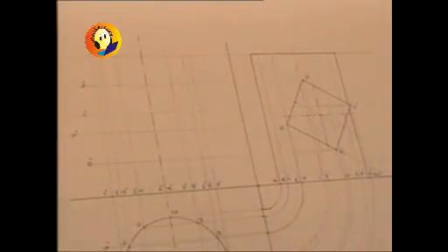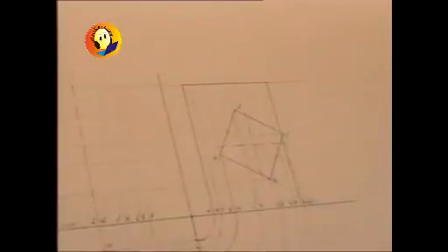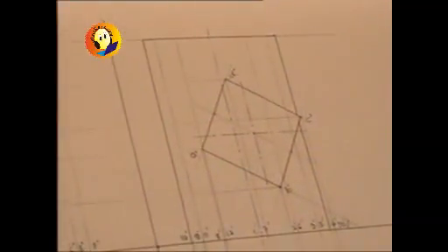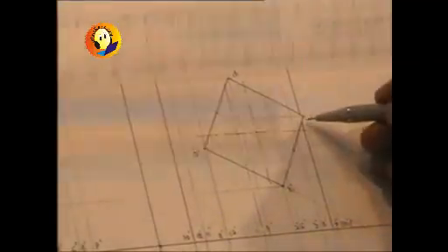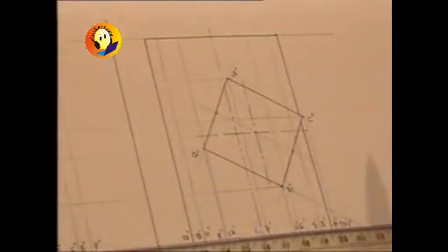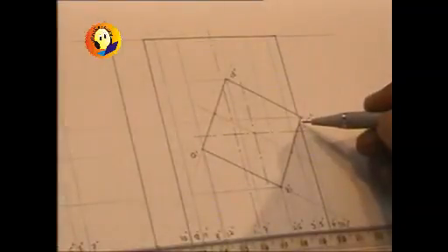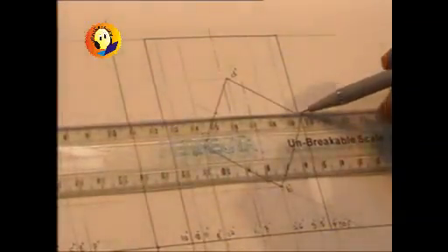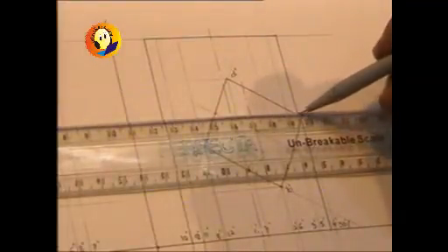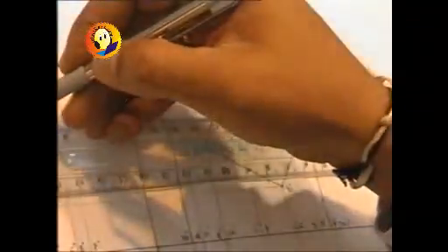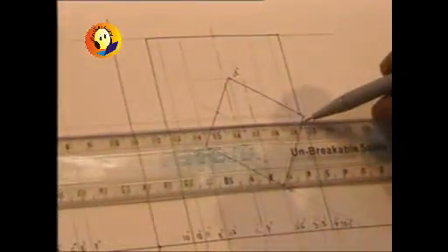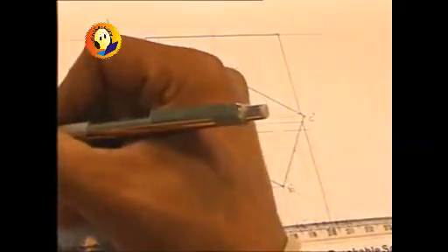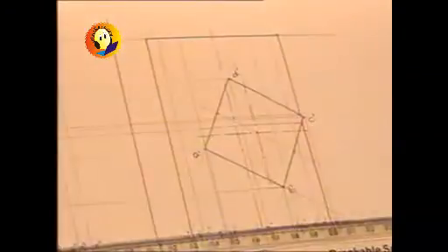Observe that side view is providing us most of the information, like generator 4 dash, generator 4 is cut at 2 points 1 and 2, and we can very well take the path from these 2 points up to generator 4 and mark the points. So 2 points on generator 4, they are marked 1 and 2.